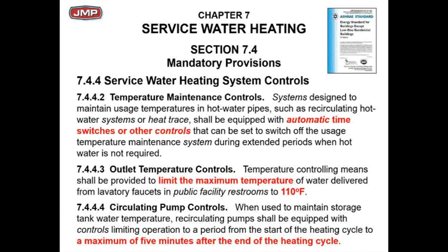The reason it's running this extra 5 minutes is to take any residual heat out of the water heater when you turn it off and put it in the storage tanks. That's a whole lot more efficient than leaving the heat over there and not doing anything with it. But why continue running the pump once it's pulled the residual heat out? Pretty basic, pretty simple stuff. But here's the message from the 90.1 2010 Energy Code: cycle the pump, turn it off.